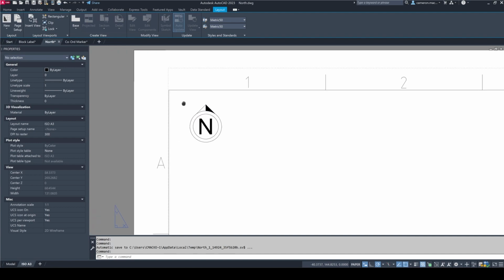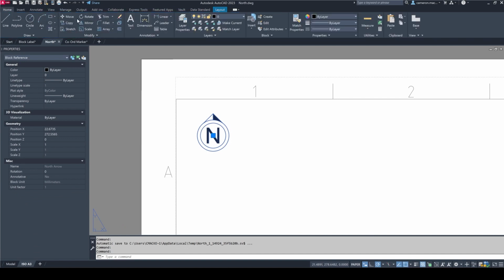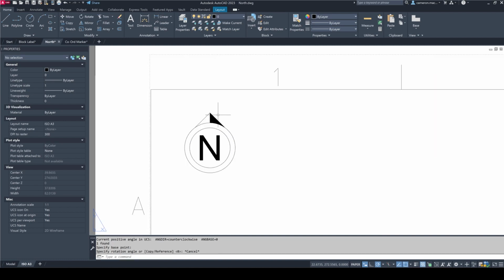You can have it as complex or as simple as you like as part of this process. But what we often get with these ones then is if we have to change the angle of that arrow, sure, we could use a rotation around the center point. If I go and grab that center point, but then obviously the letter flips around, so that only works in some angles really. If we want to have a 90 degree or 180 degree, it doesn't quite do what we need it to. So the way around that then is creating this again as a dynamic block, being able to make a change to the object that will allow us to have variations of the design itself. Again, that's the whole point of our dynamic blocks, is to be able to create variations of a single design.